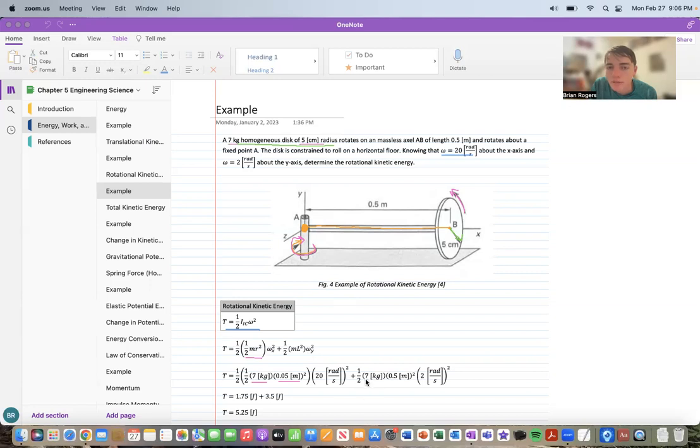And so what we're going to see here is, remember that axle is 0.5 meters. And so we know specifically the mass they gave us in the problem and 0.5 meters, so it's the length of that axle. Remember, because the axle is just of length L, you use the ml squared for the instantaneous center, calculating that moment of inertia.